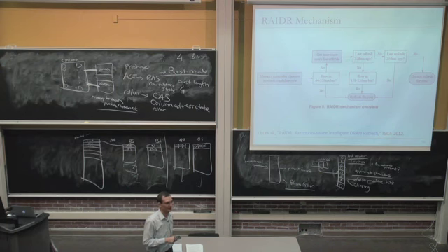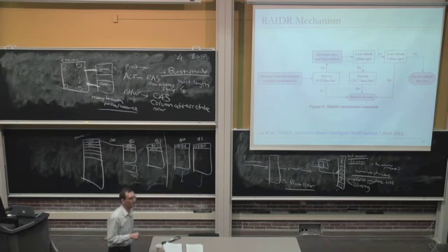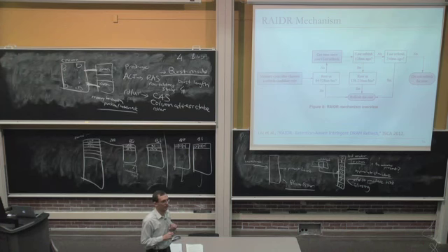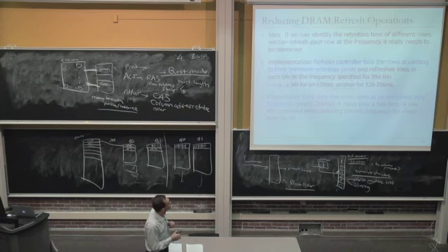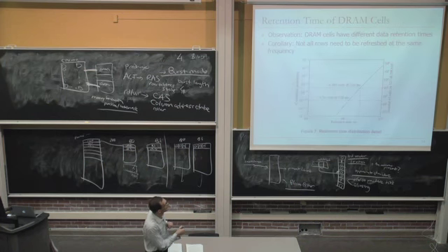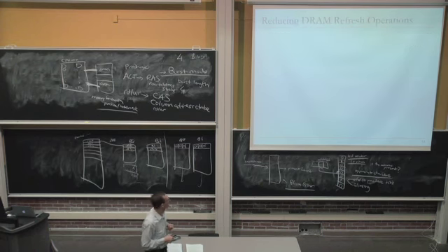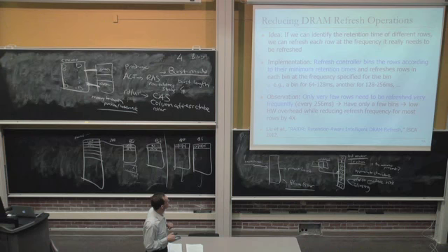That's right, exactly. So how do you decide the size of the bin? Is it conservatively decided, in case you have such a badly manufactured chip? Yeah, so that's a design choice. You're absolutely right. If it turns out most of the DRAMs follow this distribution, your size doesn't need to be that large. Okay, but those are good questions.